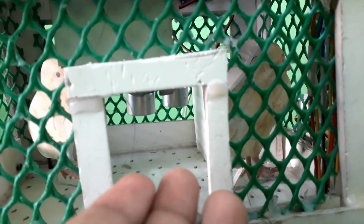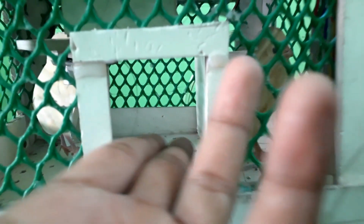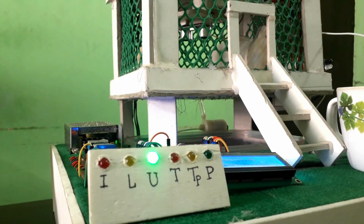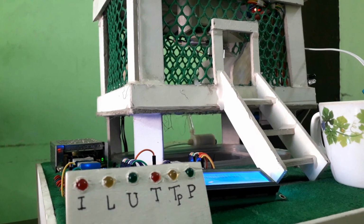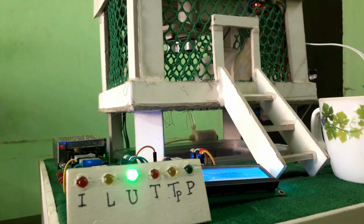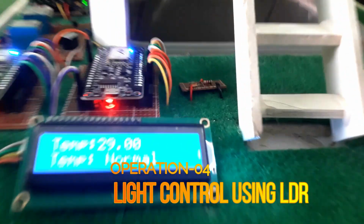Now we will make sure of the proper distribution of feed for our poultry, and in this case we use an ultrasonic sensor. When feed is available more than required, at that moment it will be closed by using the servo motor, and when the feed comes down to a low level, at that moment the ultrasonic sensor will open the door for feed.